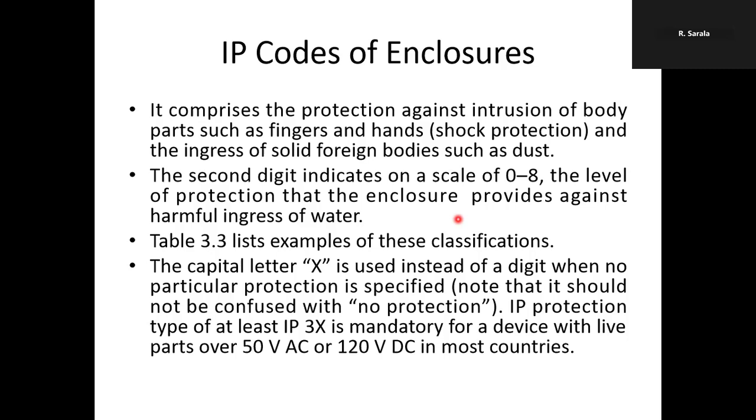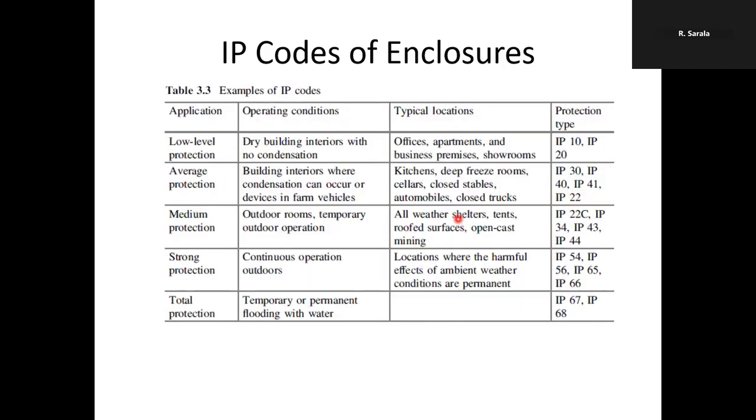IP protection type at least IP followed by 3X is mandatory for a device with live parts over 50 volts of AC or 120 volts of DC in most of the countries.